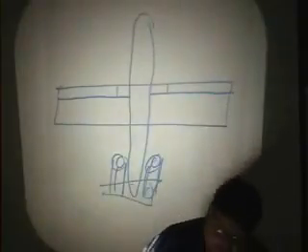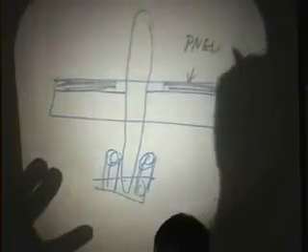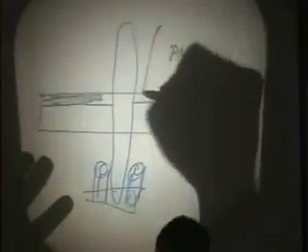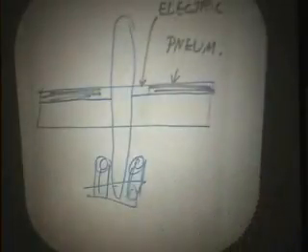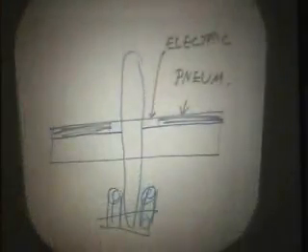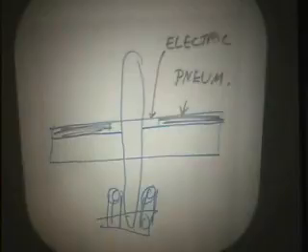And this outer portion of the wing right here, they're pneumatic boots. They inflate and deflate. But right in here, it's electric. Now if you ran the electric anti-icing all the way out, the whole leading edge of the wing, it would take a lot of electricity. You'd need a bigger generator on board the airplane. The empty weight of the airplane would go up, and it would burn a significant amount of fuel to run this generator. So they only make part of it electric.